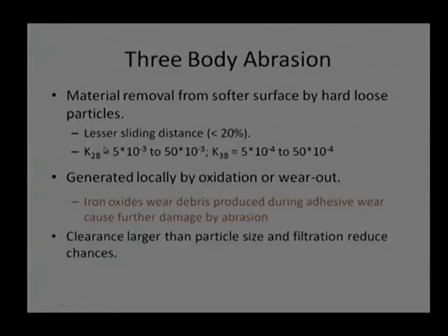That is why if I compare the constant K for 2 body abrasion and 3 body abrasion, wear rate is a non-dimensional number, and it may be say 5 into 10 raised to minus 3. This is just an assumption. I am not saying that wear rate will always be like this; it depends on the material combination. But if the wear rate is something like 5 into 10 raised to minus 3 for one tribo pair, then for 3 body abrasion, it will be reduced by 10 times. It will be 5 into 10 raised to minus 4. Again, it is an approximation, not an absolute value, but chances are wear rate will decrease significantly, maybe say 1 order of magnitude.